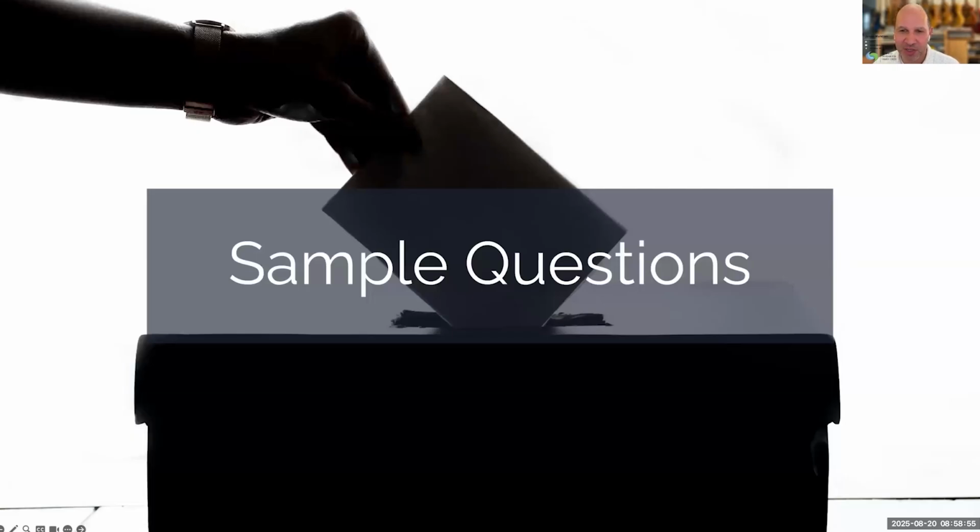Larry, can you skip question 2 and go straight to question 3, which is the slope question? This is a quick slope calculation question. What's the slope of a pipe that has a 2.5-foot drop over a 100-foot length? Simple equation. So the correct answer is 0.025. Remember, it's drop divided by length, so it's 2.5 divided by 100, which is 0.025.